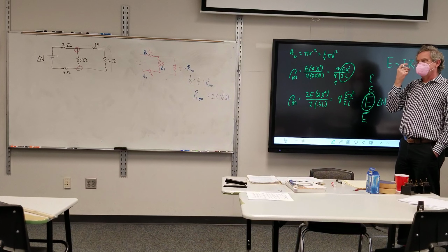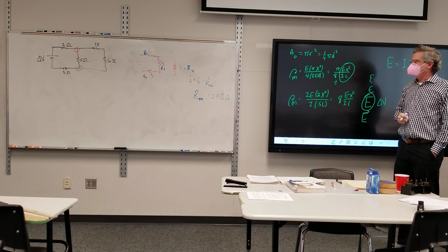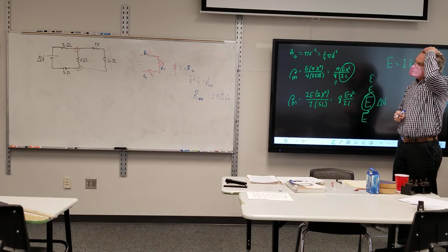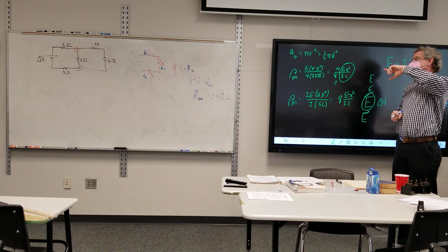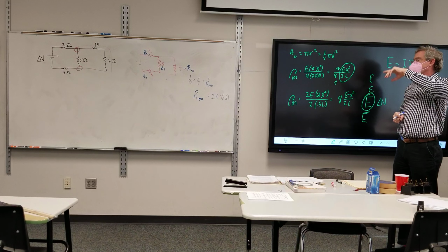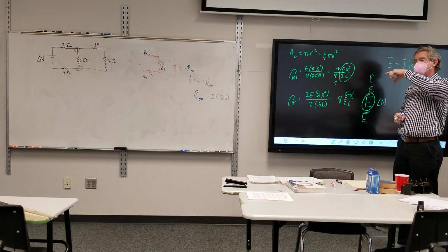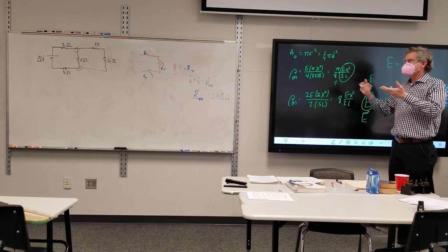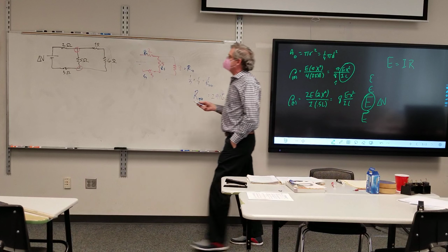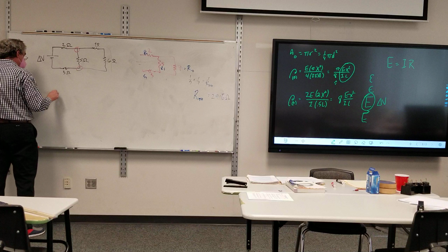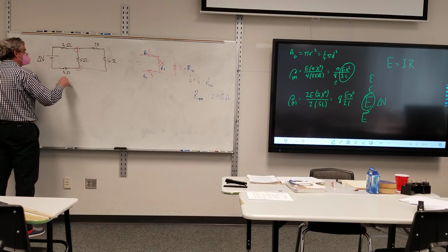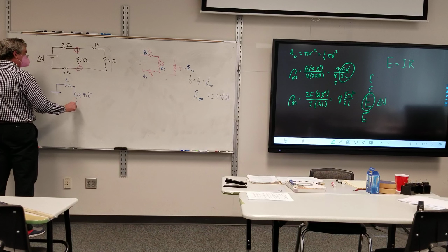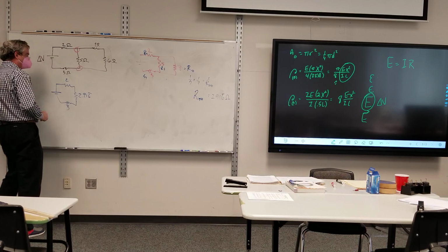Well, I know it's gotta be less than 5. If I'm adding in parallel, my equivalent resistance has gotta be less than any of my individual ones. Also, if they're the same, it would be cut in half, so I got 1/5 plus 1/7. If they're 1/5 and 1/5, I'd have 2.5. And so, ballpark seems reasonable. So I've now broken this down into 2.916 repeating, and 3.